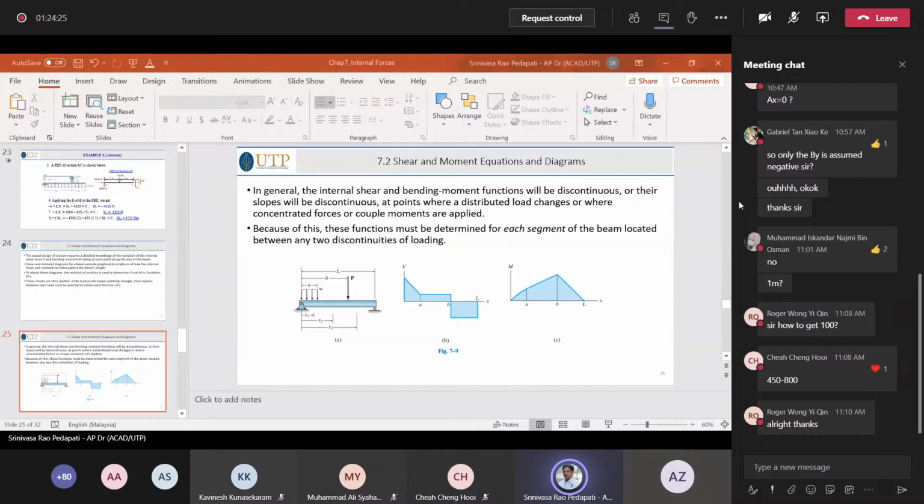So in the case of the beams which I showed in the bridge, or in the columns which are wider, the moment acting at the bottom is more compared to the moment acting at the top of that billboard, because moment is force into distance. Force into distance at the bottom is the distance of the whole pole, whereas in the middle it is not the whole pole. That is why we want to reduce the weight, so we reduce the material at the top.